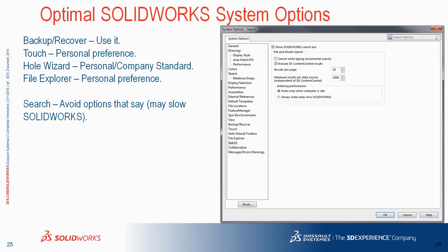What I would do with backup and recover, more important than anything else, is to use it judiciously and not set it to like auto-save every 6 moves or something like that, because especially if you're using large assemblies, that can definitely be detrimental. We've actually had customers that had it set to do the auto-save so frequently that it wouldn't finish the save before it had to start again. So when that happens, you get caught up in a loop and your performance, well, quite literally goes to pot. It's just awful. So be very cognizant, especially the autosave feature, what's going to happen.